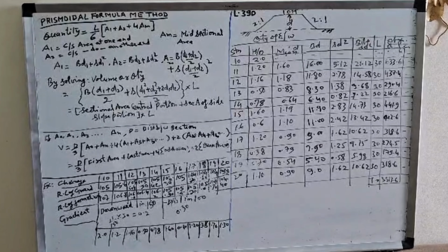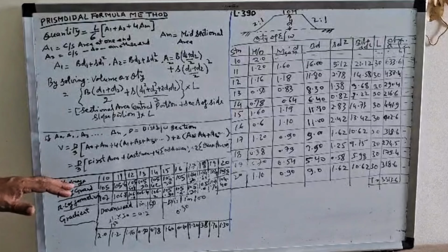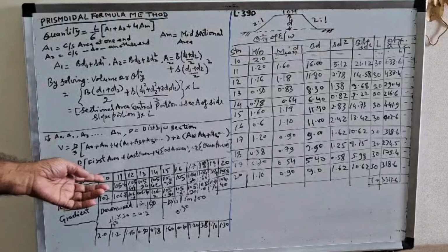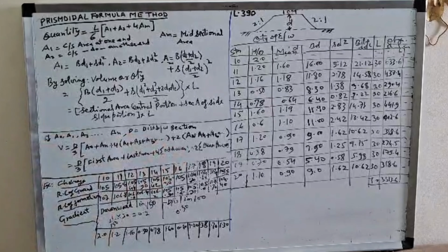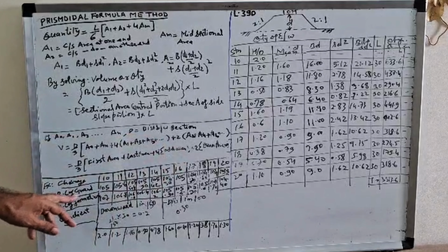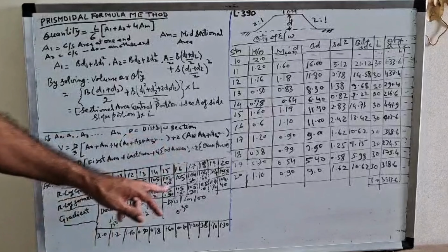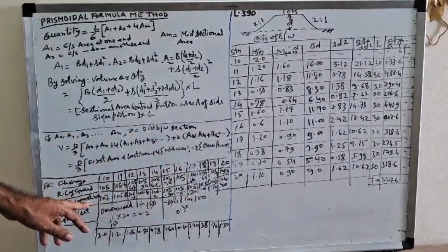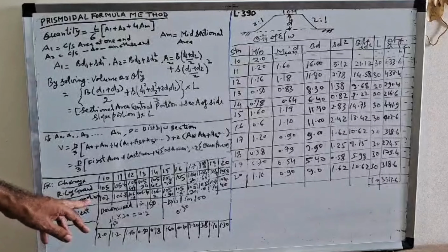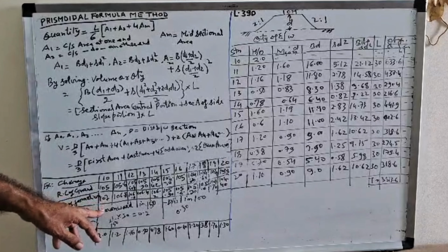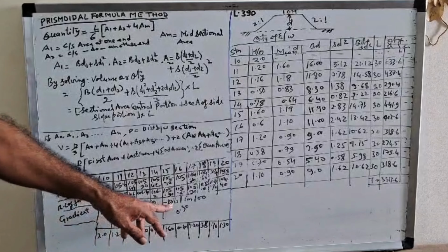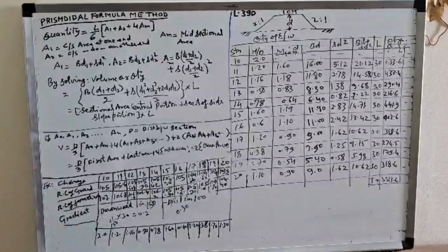So we have taken an example. Suppose for any chainage, this can be 10, 11, 12, 13, at 30 meter chainage intervals, and the RL of ground is depicted over here, and the RL of formation you can find out. This is given as 107 at this point, then downward 1 in 50 up to 14, and again downward 1 in 100 for the rest of the chainage.